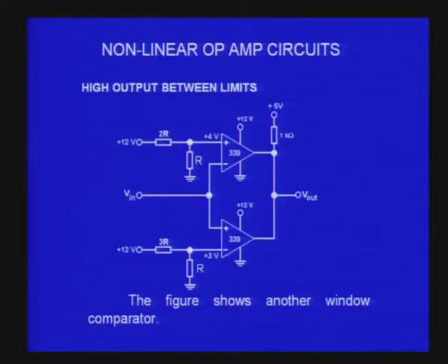So, in the circuit that you see on the screen, you can see you have got 2 op amps from the LM339 IC. This is one comparator, this is another comparator, like you have A1 and A2, and one of the thresholds, the LTP or the UTP, is obtained by using a potential divider. You could have done that even in the previous circuit. That is exactly what we are going to do when we show a demonstration at the end. These LTP and UTP will normally be chosen from the already existing VCC by using an appropriate potential divider circuit.